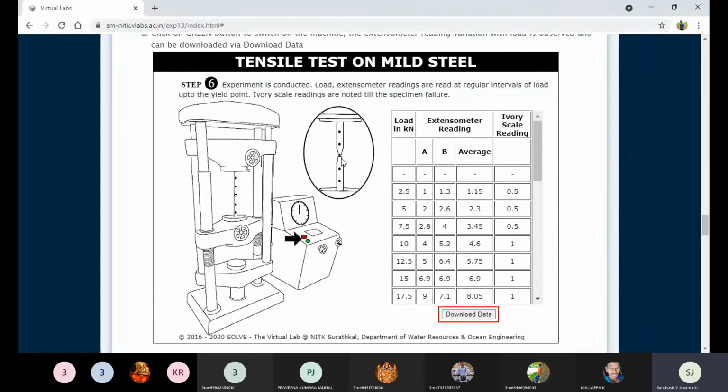Yes, here we can see the fracture takes place. At the exact middle, there is a reduction in the cross-section area. So here we can see the fracture takes place. This is how it looks once you zoom in. It looks like a cup and cone type of fracture.